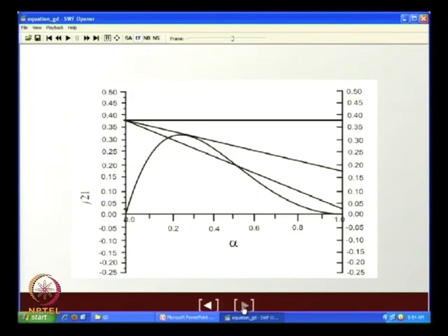Countercurrent flow with gas up, liquid down. So, therefore, gas up means J2 positive, liquid down means J1 negative, minus J1 positive, right. Is this portion clear? It is very simple. It is nothing very difficult to understand. So, for this particular case, what do we find? We find that the straight line lies entirely in the first quadrant, and if you observe, you will find that the straight line cuts the curve at two particular points.